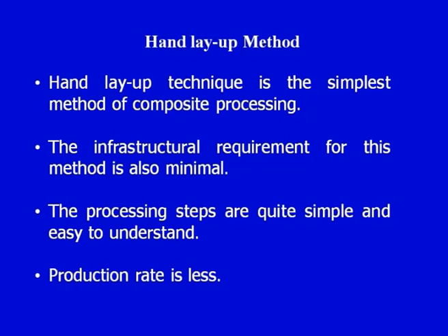The processing is very simple, the steps are very easy to understand, and the production volume for which the hand layup process is suitable is low to medium. For low to medium production volume, we can justify the use of a hand layup process. Now, as we have seen, the hand layup process is the simplest method, it is widely used, infrastructure requirements are minimal, and the processing steps are quite easy to understand.